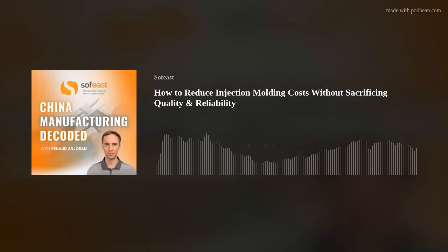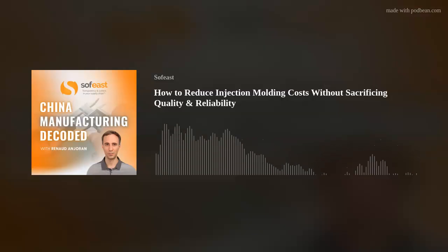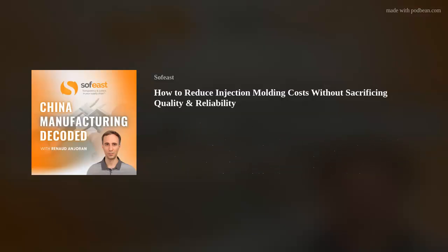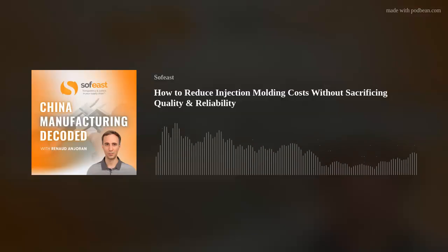So the best practice there is only apply the tolerances on critical to quality attributes or sections of the part you're designing, i.e. the toolmaker will focus on those parts and have open tolerances on areas that don't need to be held that tight. Okay, so that's the first thing. People do get carried away with, oh, I've got tight tolerances. Well, hey, look at us, we're heroes. Not necessarily the case. You're just adding unnecessary time and cost there.